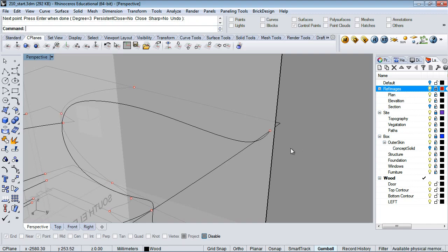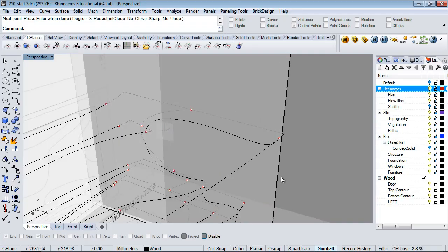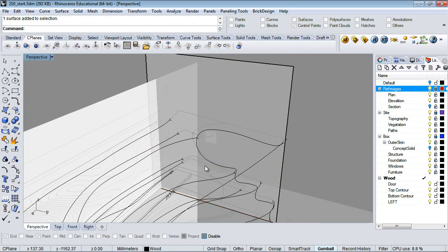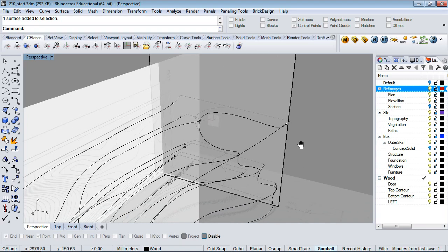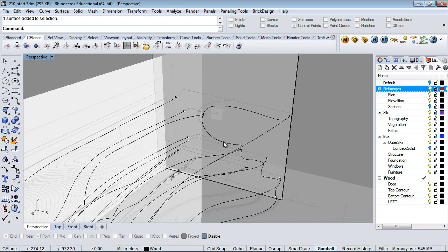Okay. So you notice that even though I said I was only really concerned about going to this curve, I drew the whole curve. What that allows me to do is to arbitrarily split this curve someplace so that I can then start and control the section. So I have some guide point in terms of tangency of what I want it to look like when I do this blend surface. So I have kind of a reference there. I just find that it's a little harder to stop and then restart again.